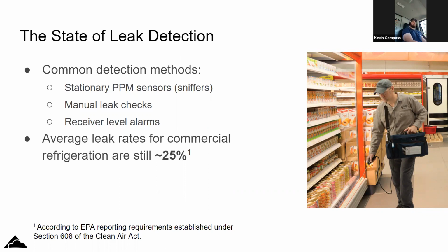Here at Client Pros, we generally have guys leak check every single time they're in a store. So you're in there for a service call, you change a fan motor, you're done in 10 minutes, you grab your leak detector and do a quick 15-20 minute leak check. I'm not talking about going on top of every single box, but you run the racks, you run the cases, check the condensers, and make sure nothing's leaking. I don't know how many times I've been in a store and found leaks that way, and then prevented refrigerant loss.